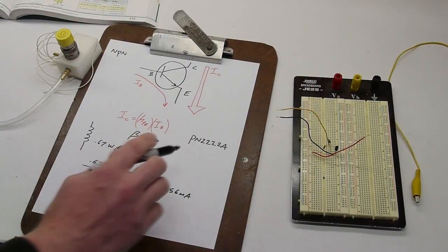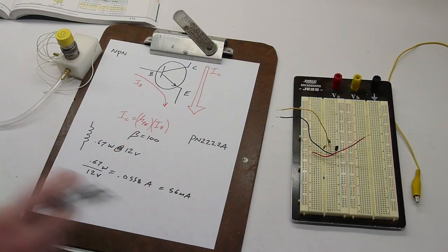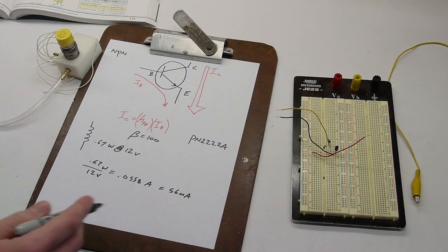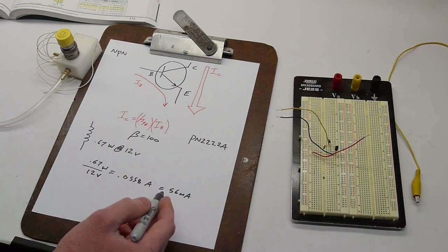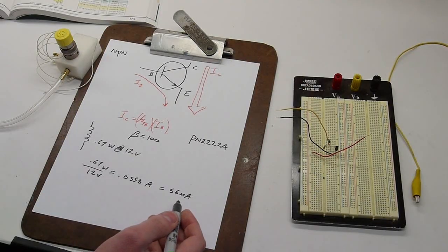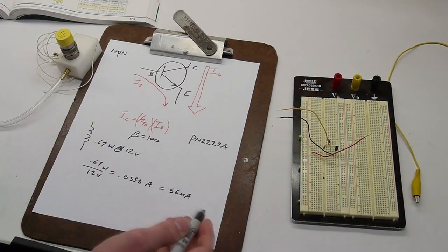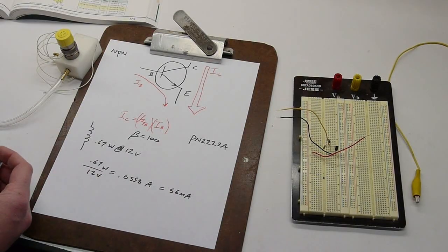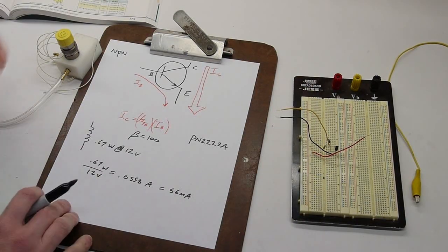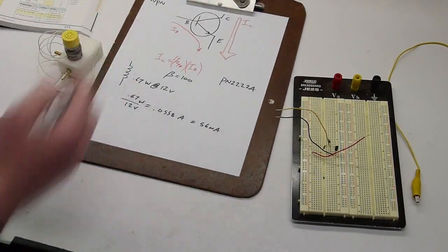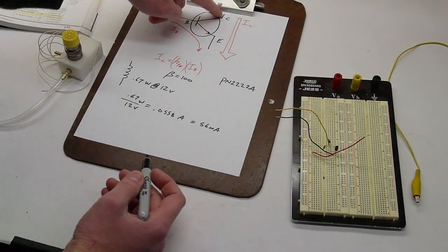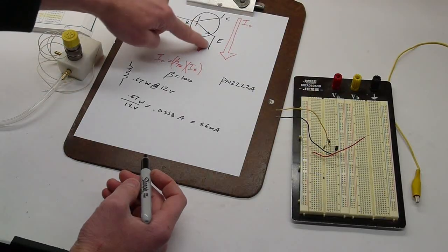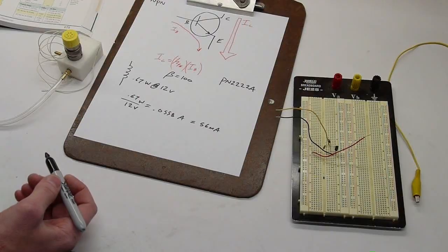So if we didn't know which transistor we were going to use, you could just start looking down the list of transistors in a catalog and think to yourself, well, the transistor is at least going to have to handle 56 milliamps, although you'll find that pretty much every single transistor can handle more than this. So this is not a very big requirement here. So what we know at this point is that we're going to use an NPN transistor. It has to handle 56 milliamps from the collector to the emitter. And now we need some way of turning the thing on and off.